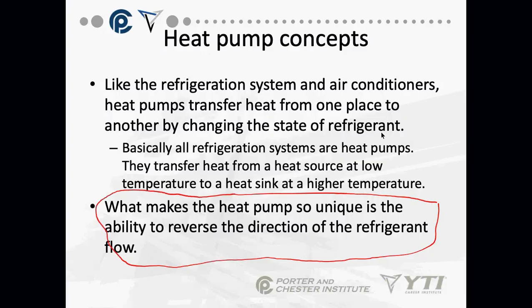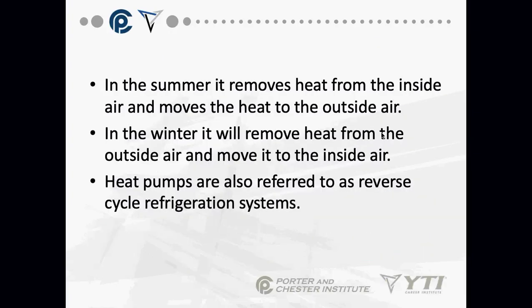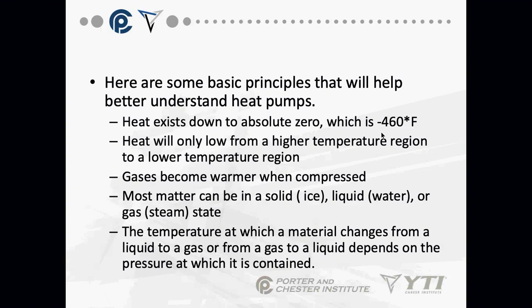I can change the direction of the flow. In the summer, it removes heat from the inside air and moves heat to the outside air. In the winter, it removes heat from the outside air and moves it to the inside air. Heat pumps are also referred to as reverse cycle refrigeration systems. You'll see that terminology on occasion. Reverse cycle refrigeration system is a heat pump.